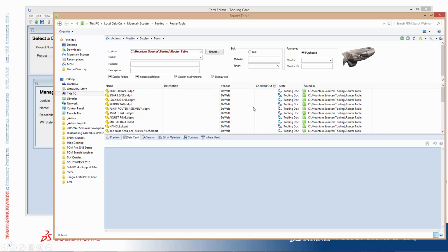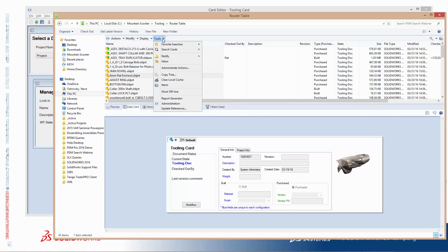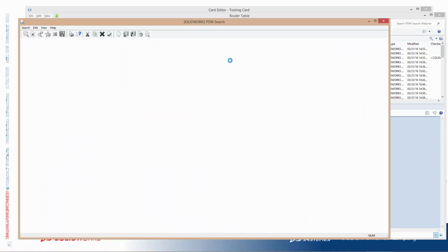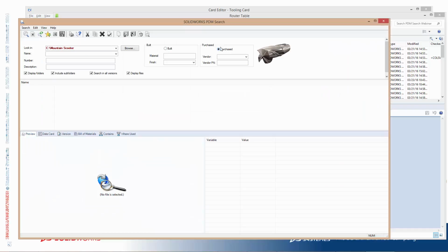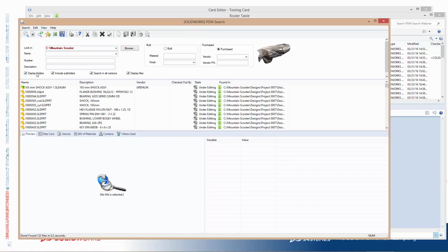And like I said at the outset, those of you that use a lot of spreadsheets to manage reports, building your column sets here can a lot of times replace those spreadsheets. And here's a great little tip to that effect: if you don't use this pull down over here and instead use the tools menu up here, this will launch a separate interface, and now when I run purchased, this will show me everything that's purchased, and in fact we can now see that there are vendors missing.